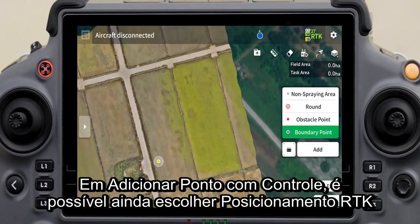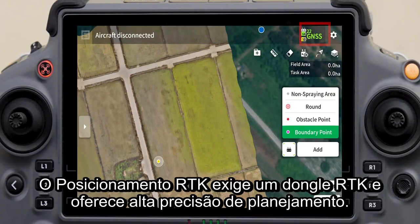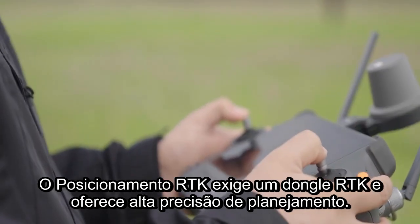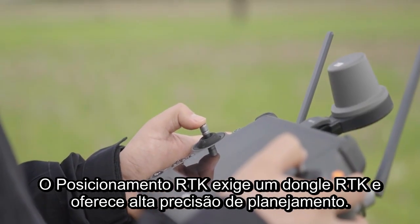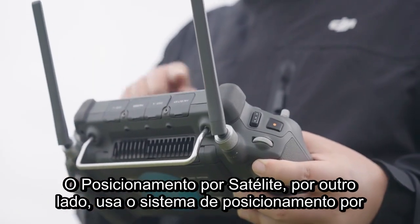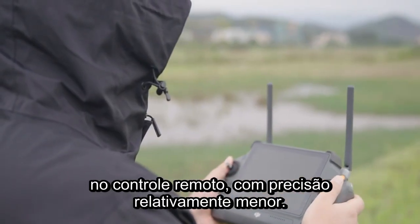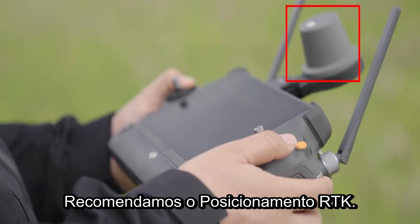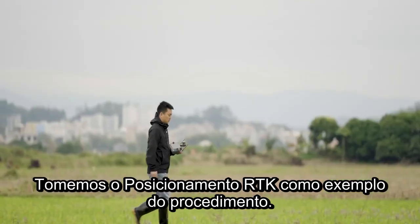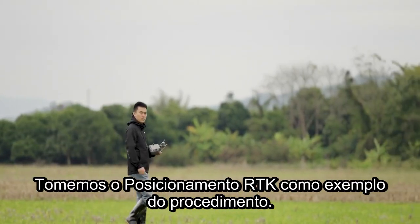If you select Add Point with Controller, you can further choose to use RTK positioning or satellite positioning. RTK positioning requires an RTK dongle, offering high planning precision. Satellite positioning, on the other hand, uses the satellite positioning system built in the remote controller with relatively lower precision. We recommend that you use RTK positioning. Next, we will take RTK positioning as an example to introduce the procedure.